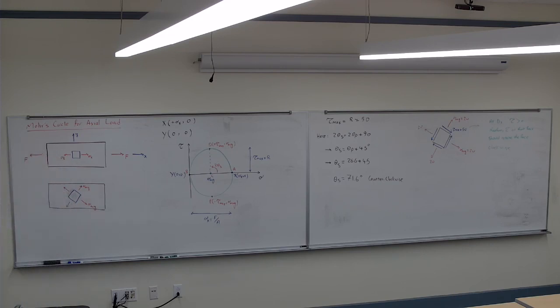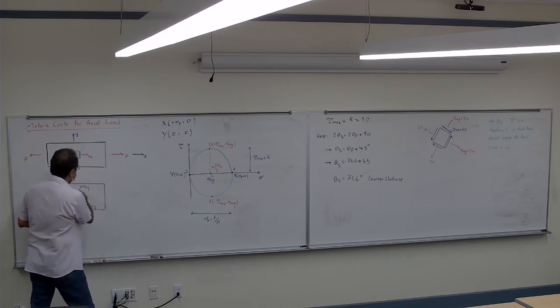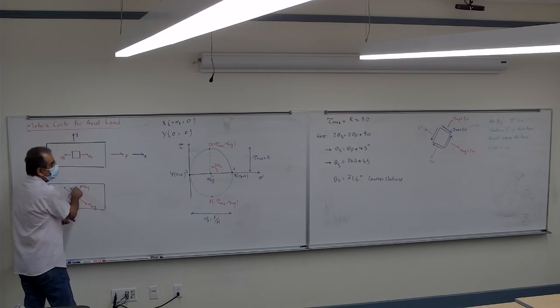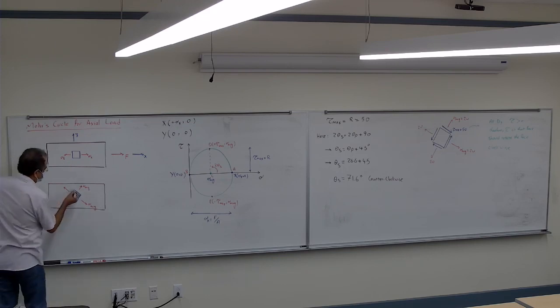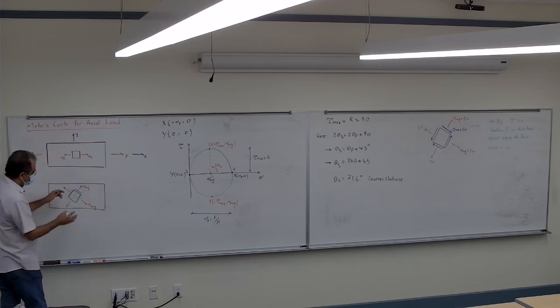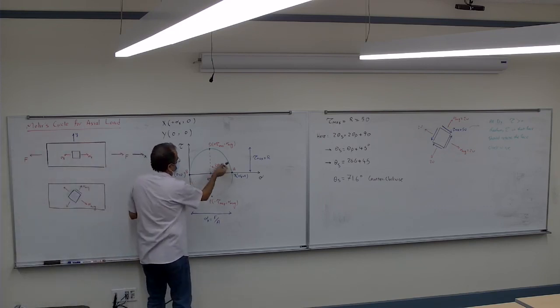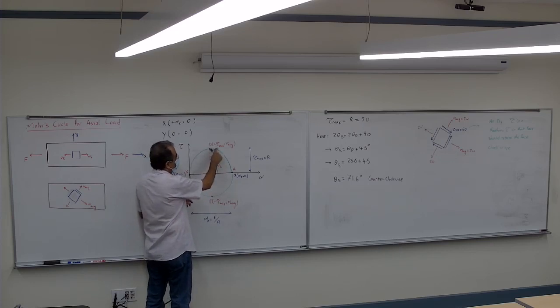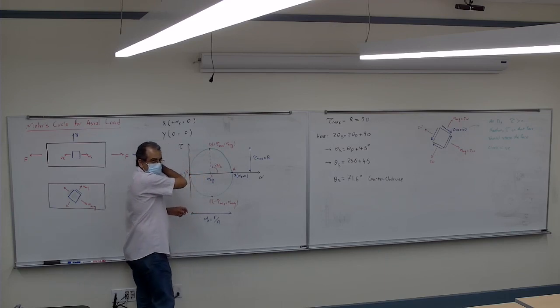And what about the tau? So tau here, in this face, is it going to work clockwise or counterclockwise? So it's going this way or this way? So this is my face. This is sigma, rotated to sigma max. The tau is positive, so it's going to be clockwise.